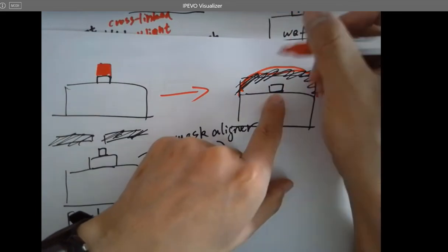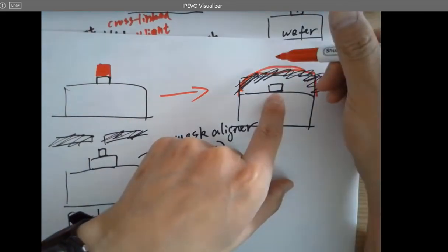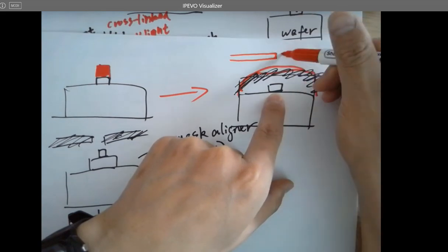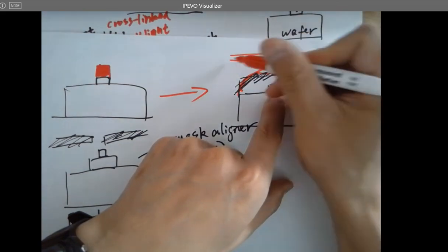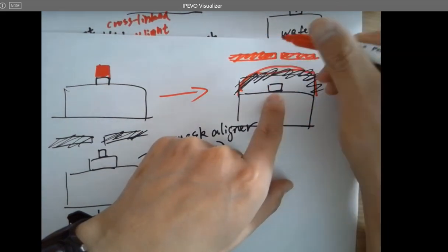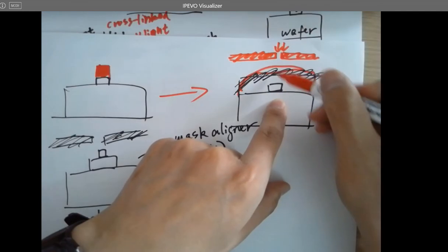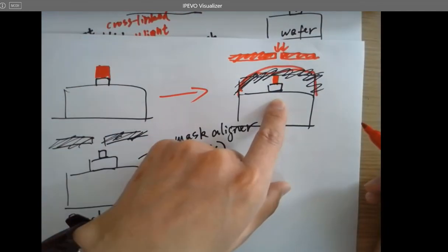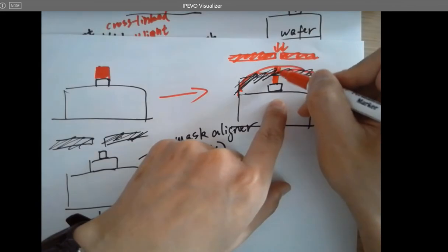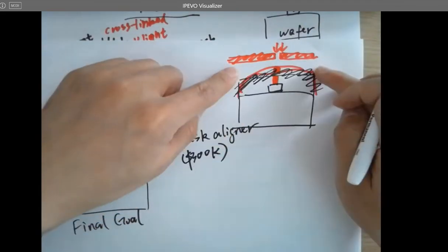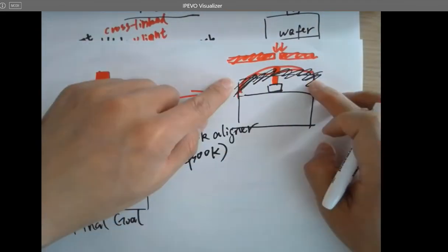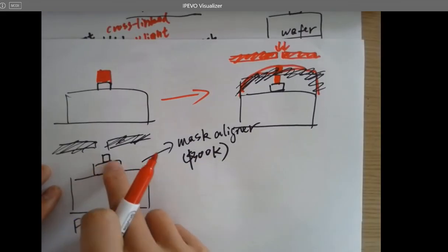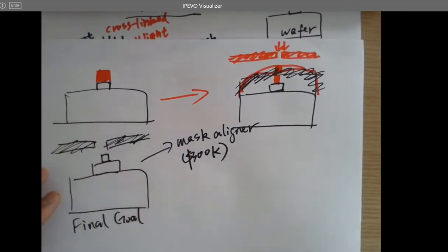And then you apply a photo mask, only leave a little opening here, and expose UV. So this little area will be cross-linked. And then remove the rest of the photoresist, and then remove the rest of the metal, so you have only a little metal dot sitting on the top of this first metal layer.